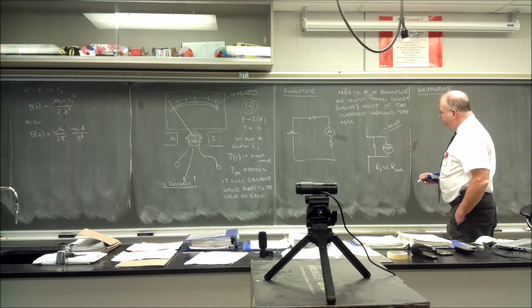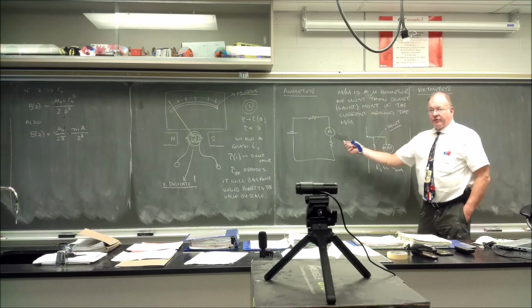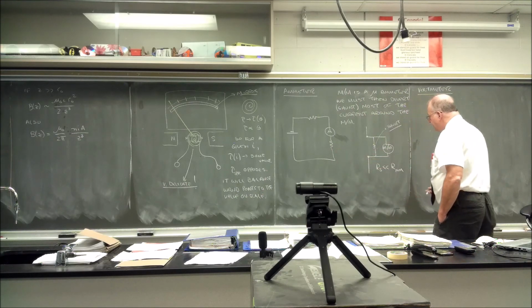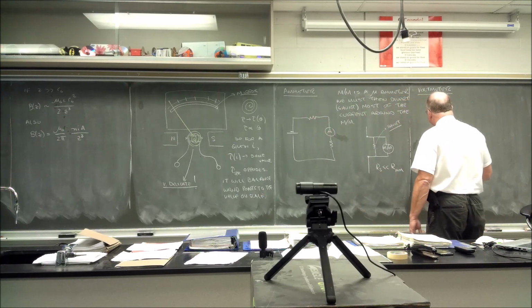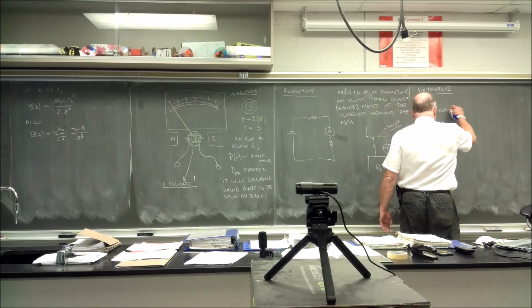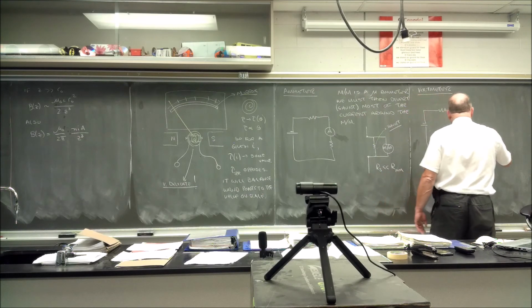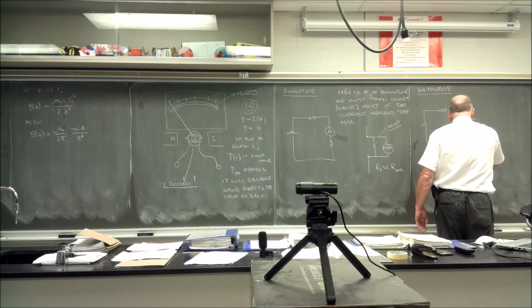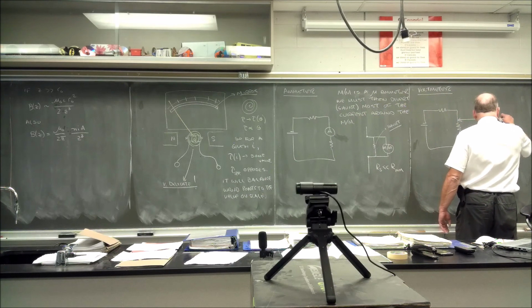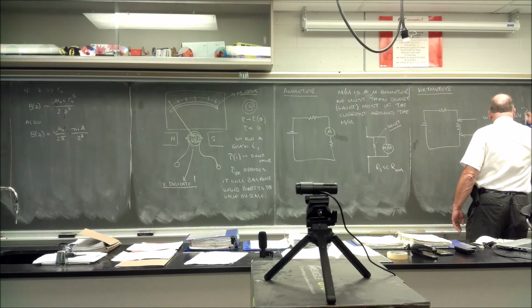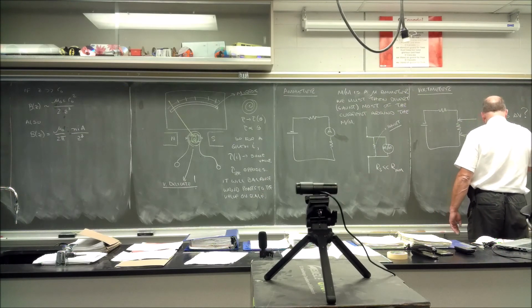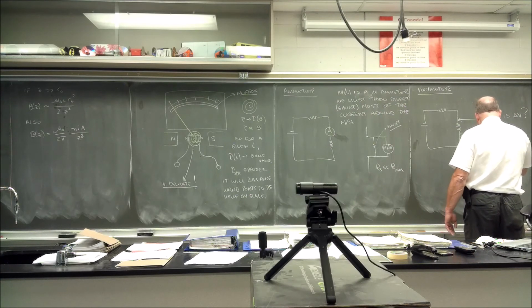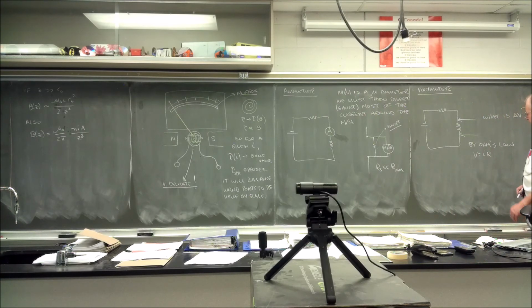And even in this case, we don't want this thing to subtract from this circuit, right? That's important. And with this being so low, it's not going to modify the current materially from those two resistors. But on the other hand, we have the same circuit here again. Now we want to know, say across here, what is delta V? Now, by Ohm's law, V is equal to I times R. Now, here's the point, is that we can choose our resistors very carefully in the meter.